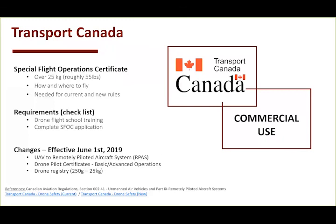Well, the only issue you're going to have with FLIR is heat. That's a big thing, because especially at night, you have warm ground cooling off, and that temperature is always changing as you're flying the scene. So unless you have a constant heat source, you're going to have some issues, because that big dot might show up at the beginning of your scene and be a little small speck at the end.